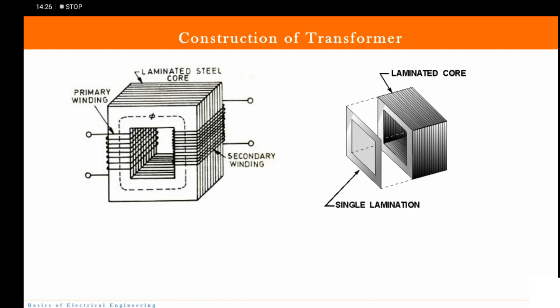Fine. Now one more loss is there which is called hysteresis losses, which we have studied in our earlier classes, and we know that hysteresis loss can be reduced by using soft steel material. So here we use very high grade silicon steel. Okay, these are called soft materials. So here the hysteresis losses are less.